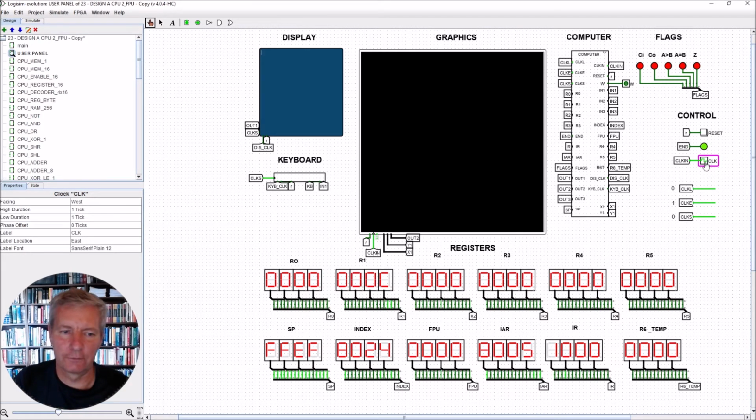But you've done this several times before and in the first course, so you should be able to go through and have a look through this for yourself. And you can actually see here at the bottom, you can see the stack pointer here is actually dropped by a value of 1 because we're using the stack in order to save the return address. So that's well worth going through at least once. Now let's finish this off and we will have a look at the write loop, and then we'll put them together in one program.